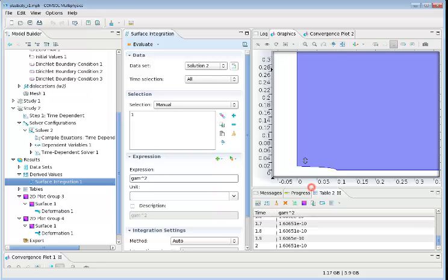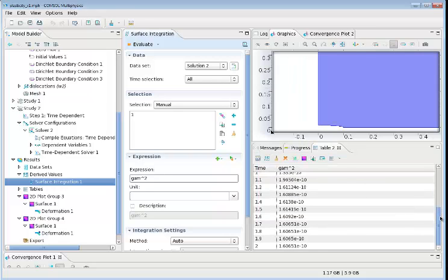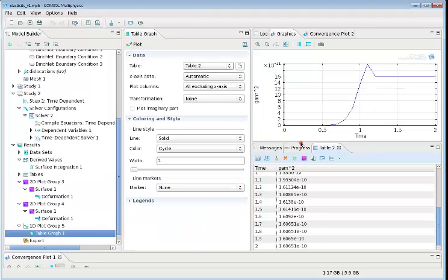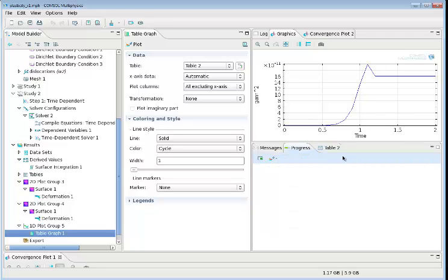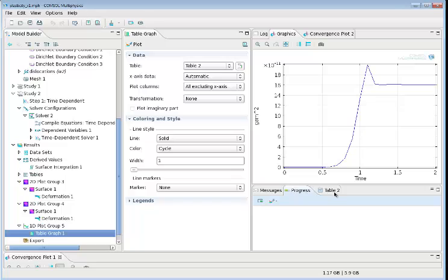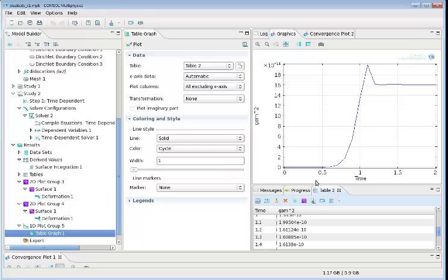If you want to further check that, if you click this button, oh, so that's interesting. Overshoots. In that case, what I want to do, so I want to go back, reduce our time step. Let's rerun this now, see if these results will be any different. That could create an instability.